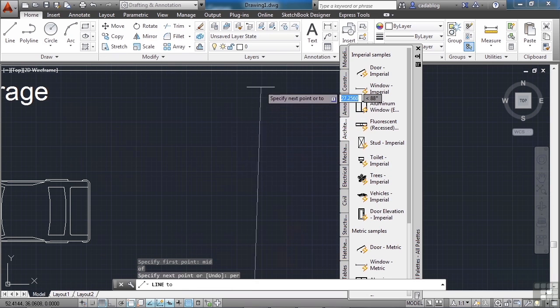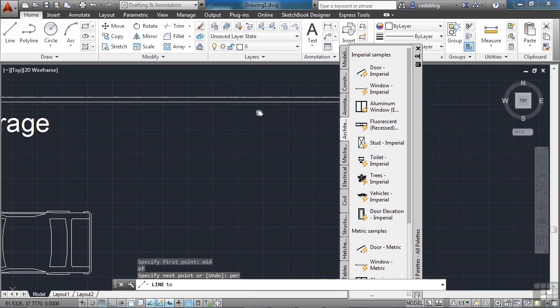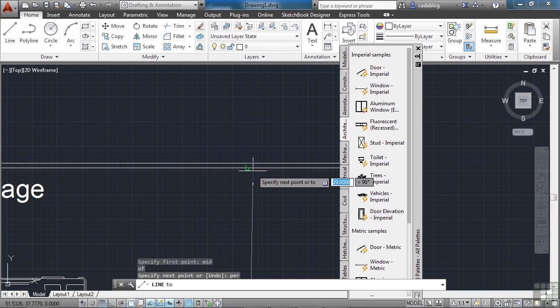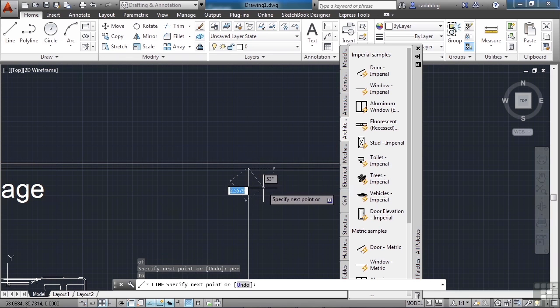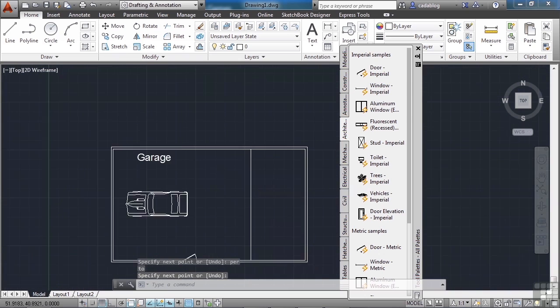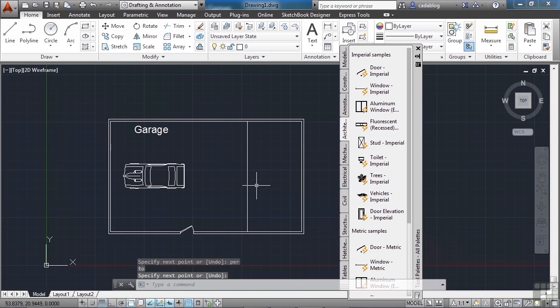And we're going to zoom in a little. You can even pan. And you see that little right angle looking symbol for the glyph? That's for a perpendicular O-snap glyph. Left click. Press enter or escape to finish your command. And you just drew a line.